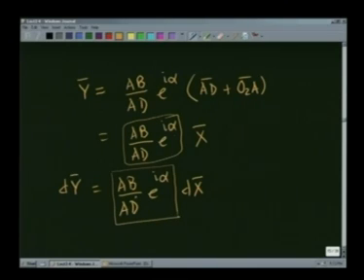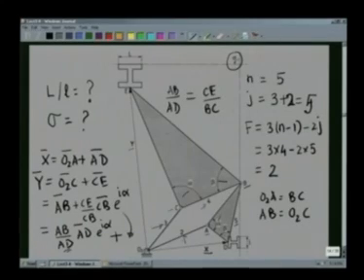That means the movement is magnified by a factor AB by AD, which is the scale of reproduction which I wrote earlier, L by L, and there is a rotation through an angle alpha in the counterclockwise sense. So, sigma, that is the change in orientation of the reproduction, is equal to alpha. To make it clear, let me go back to the previous slide, that AB by AD, that is the factor of reproduction, that is this length by this length, that is this letter h is reproduced to a bigger scale, namely by the factor AB by AD. Not only that, this vertical side, which is vertical like this, has been oriented through an angle sigma, and we have already shown that sigma is nothing but the angle alpha.